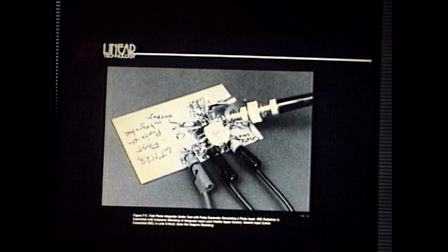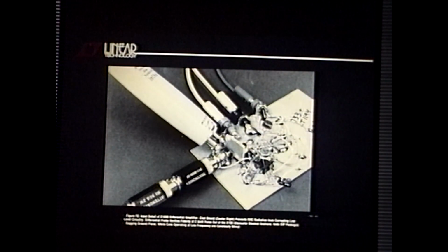You don't worry about inductive coupling? Question, I'm not worried about inductive coupling where? Well, you've got current loops there. I mean, the attenuator current has to be flowing somewhere in the track. The attenuator current is flowing into the attenuator and right back through its coax out. But that is loop current there. That's a loop, but if the attenuator guys have done their job and this thing is truly coaxial, it should be okay. That's why I never, don't even think about trying to build your own terminators or attenuators. You know, you can't do what they can do.